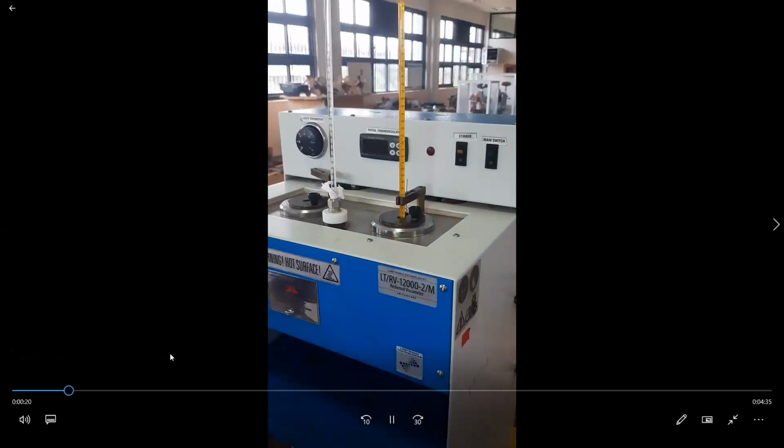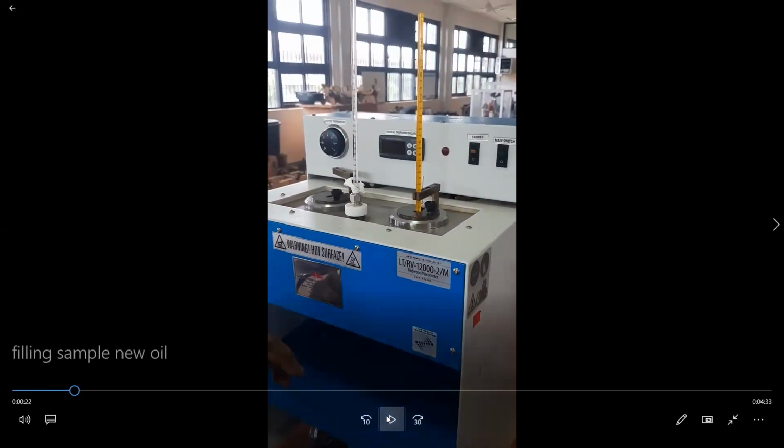Already I have done 60 and 70 degrees Celsius. So now we are going to do it for 80 degrees Celsius, right? So every time, let's say we are going to measure the viscosity at 60 degrees Celsius, we have to put the sample here and heat this sample up to 60 degrees Celsius. Then after reaching 60 degrees Celsius, from this thermometer we can observe, no?